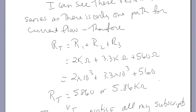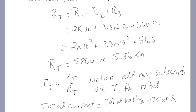Therefore, the total resistance is equal to the sum of the three resistors. So I just put the three resistors in and add them. Notice when I add them, I don't just add 2 plus 3.3 plus 560. I need to convert the K to thousands. So it's 2,000 plus 3,300 plus 560, for a total of 5860, or moving the decimal place over 3, 5.86 kiloohms.